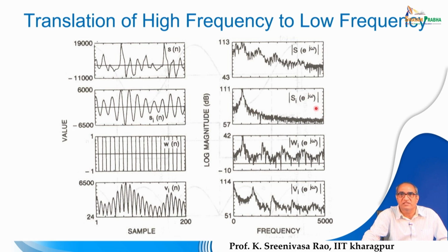And our goal is that all these critical frequencies have to be shifted to the lower side. For that, we apply a non-linearity. That means whatever narrowband signal is there, we multiply it with rectangular pulses. You can see that the original signal has both positives and negatives, whereas here the entire signal is on the positive side. This is known as the rectified signal.